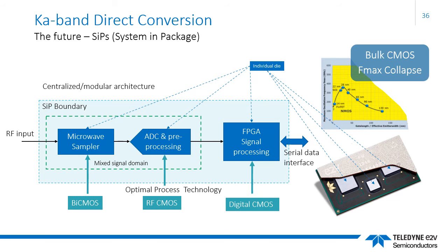Whilst lacking the optimal form factor of an SoC approach, system on chip approach I should say, SIPs still provide a micro-miniature integration route, allowing a cost-optimal selection of silicon processes for key functions. Furthermore, SIPs offer tailor-made designs, not dissimilar to giving a customer flexibility as found with traditional ASIC choices, for example.